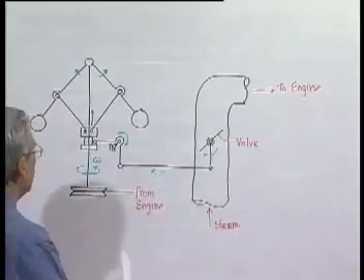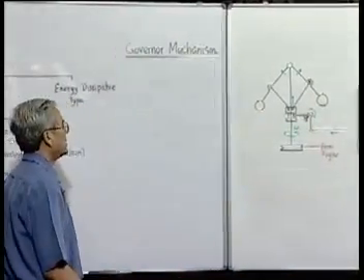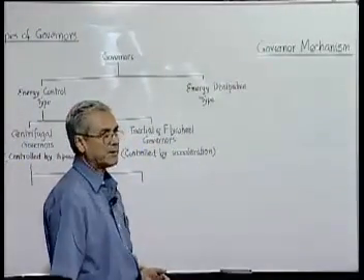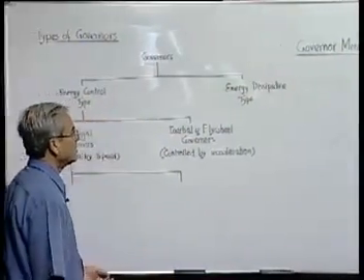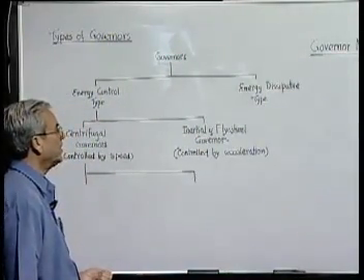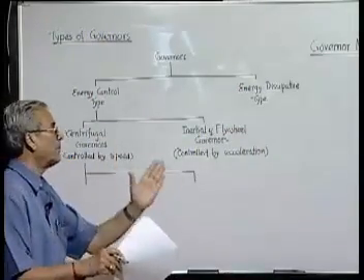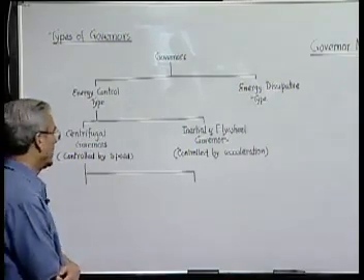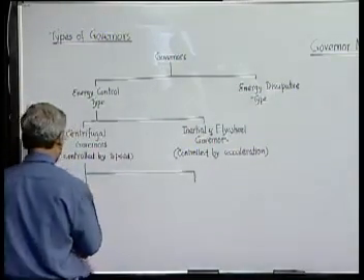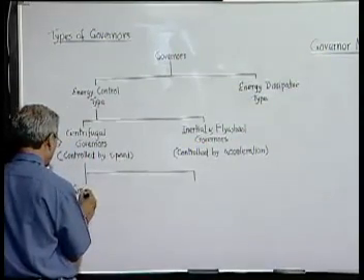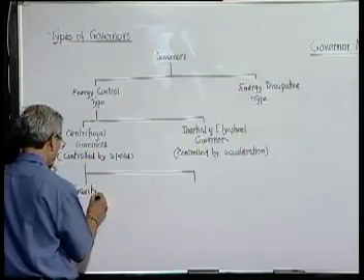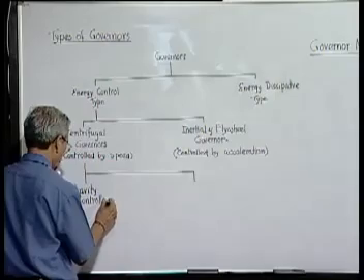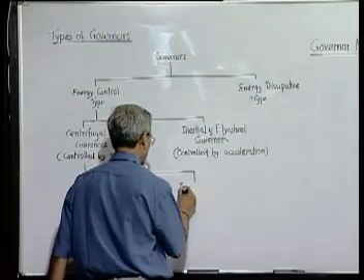So it is gravity which brings down the system, or restores the governor always to the lowest speed position or collapse position. There are cases where governor systems have been designed where the restoration to come back to some design position all the time is through a spring. So we classify them further into two groups. One is gravity control and spring control.